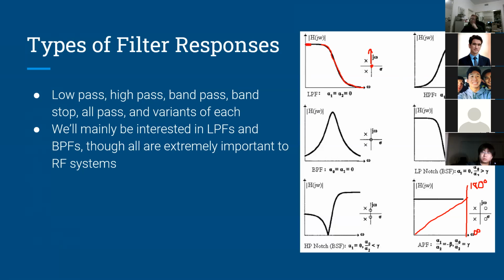And you see the opposite thing with the high pass filter, and that's because now there's a 0 at 0 frequency. So at DC, the response is 0. And as we go higher and higher in frequency, we're moving away from that 0, and that allows the frequency response to go up. And so on. So hopefully that makes sense.